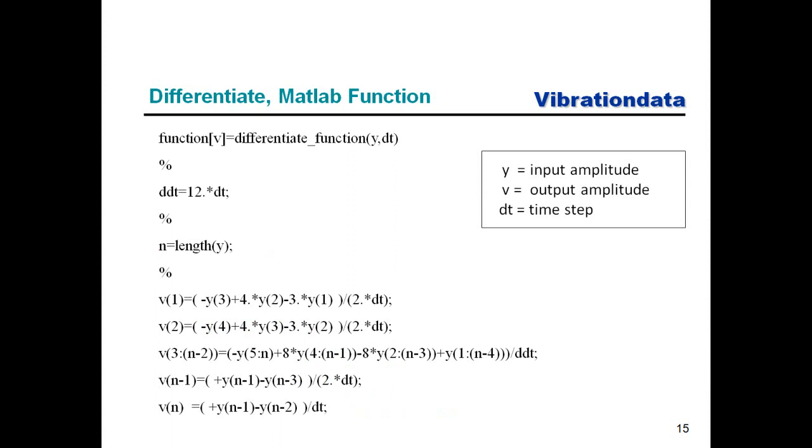For differentiation, it's a little more complicated rule. The typical way you think of doing differentiation is just take 2 amplitude points and take the difference in amplitude divided by the difference in time. That's a typical way for doing a linear slope. When we teach graphing and lines in algebra to students, we say, for a straight line, y is equal to mx plus b. Well, that m factor here, for oscillating vibration, we really need more of a robust rule.